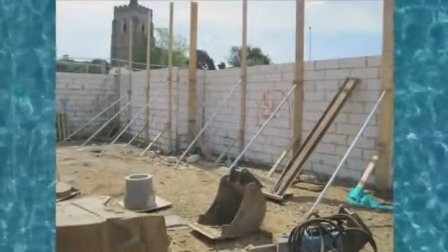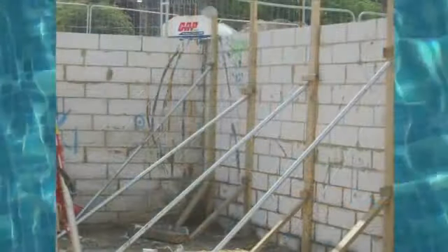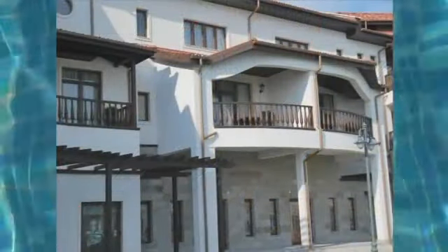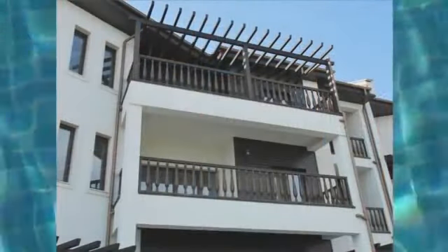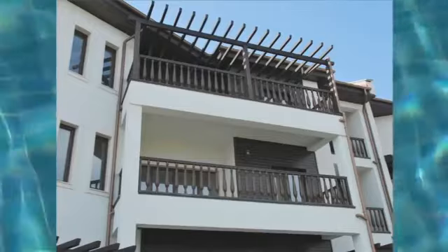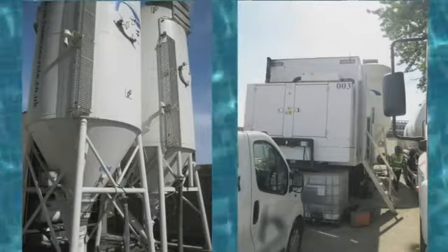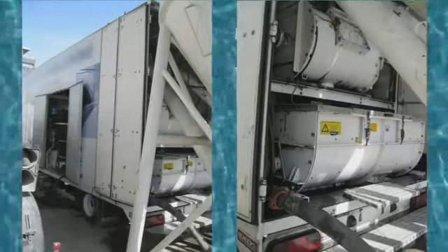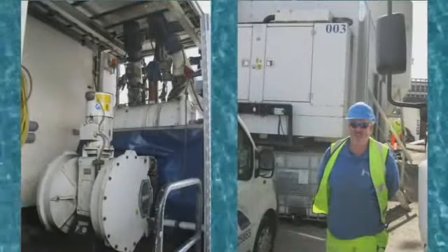The mix of CFC with water is ready for forming of different construction products: blocks for walls, overhead covering and partitioning slabs, arches, and so on. There are no special requirements for the water used. Drinking water with room temperature can be used with no restrictions. Technical water, including water from the sea, can also be used. It is, however, recommended to check its chemical composition first.